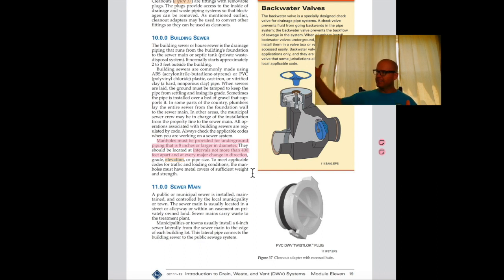If I've got my building coming into the sanitary sewer right here, I've got to have a manhole around here somewhere because I've got a change of direction and a combination, okay? So I'm going to have what is deemed a manhole, which can also be used as a clean out, and I've got a clean out coming outside of my building. Just note that there's going to be a question that's wanting to trip you up, and it's talking about the differences or where a couple of clean outs is needed versus the rest of them being just one.